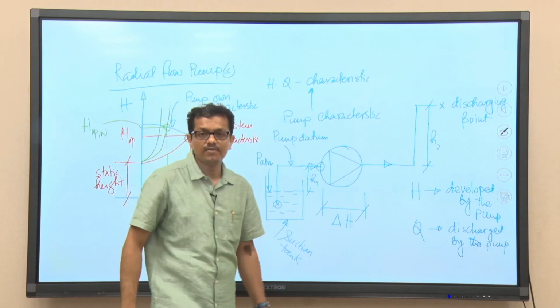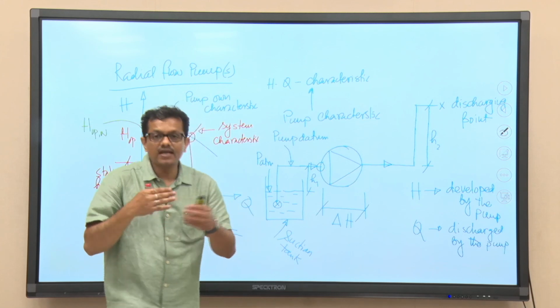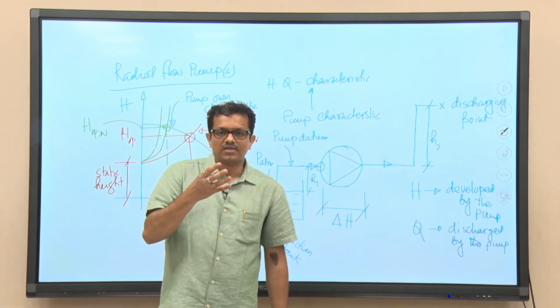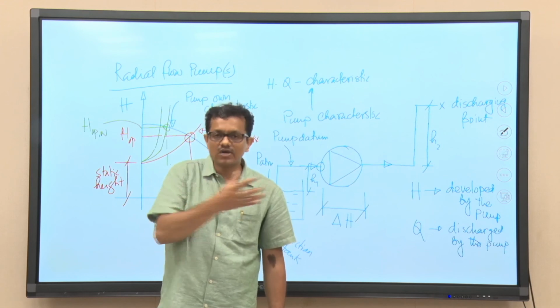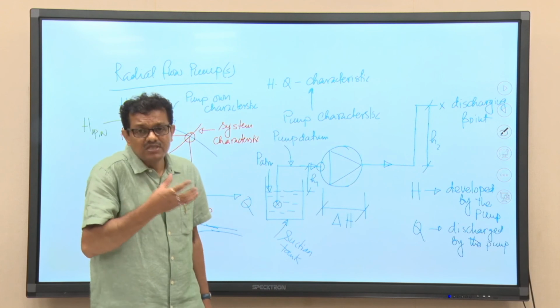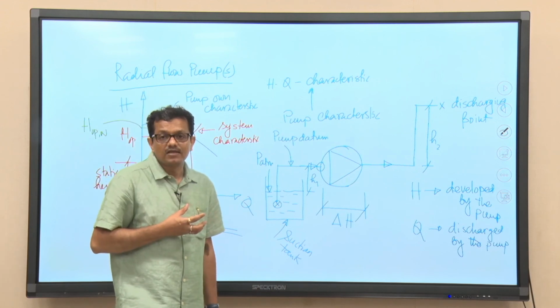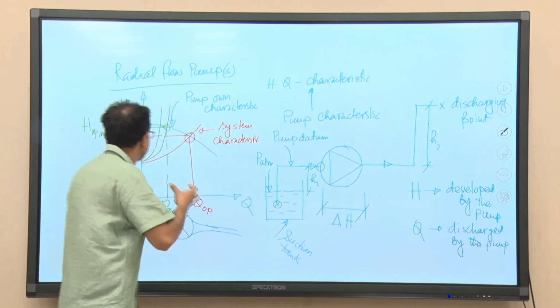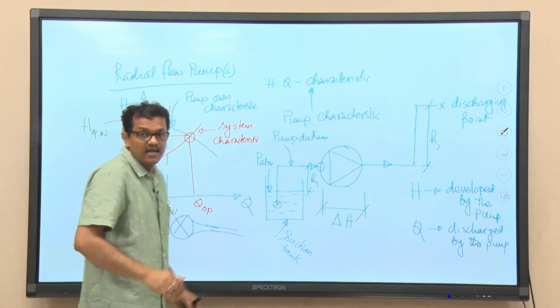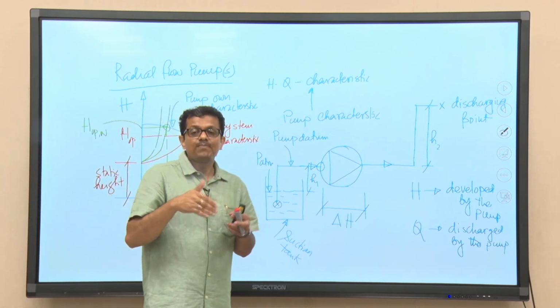What will be the problem? You will be hearing one common term, used by industry experts, the engineers who are responsible for looking after this system, very commonly: pump tripping. So the pump will trip. Why? You can understand, the head is close to the shut off head. Now, why will the pump trip?